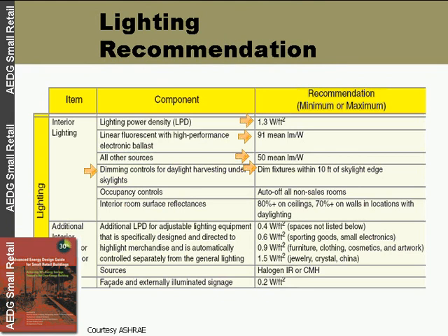We don't have any recommendations, and actually we would recommend against dimming or switching off any lights near the entry of the retail space, because that does tell the customer that the store is open. And if we shut those off, we could actually adversely affect sales. Controls, again, in non-sales areas, we want to use occupancy sensors. And again, if you're doing daylighting, we want to see those reflectances very high to bounce that light throughout the space.